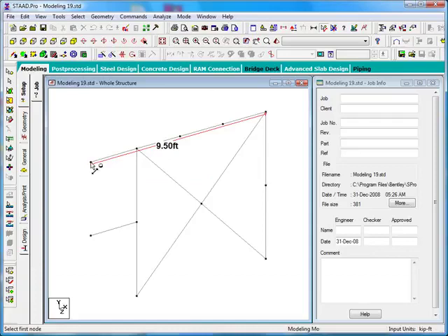Or I could click, say, from the free end of the cantilever down to the bottom of the column if I needed to triangulate a dimension and figure out what the dimension is from points in space to other points in space. Now the way that the display node to node dimension tool works as far as removing dimensions is, we have 2 options.